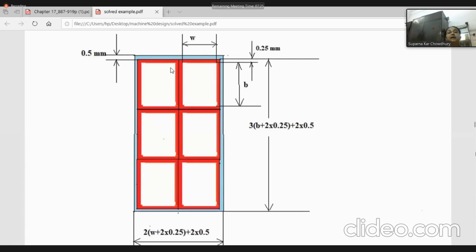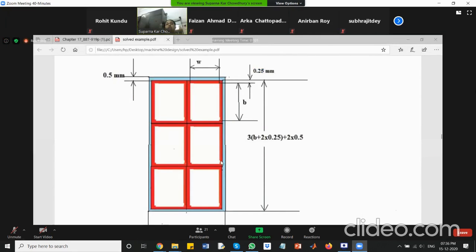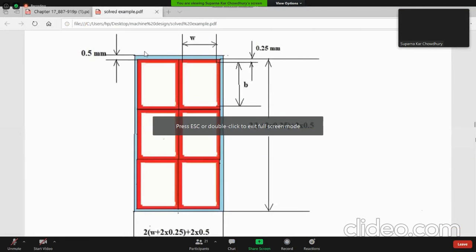So this is the bare copper on which we will have insulation. Normally this insulation is paper, double or triple paper covering, DPC or TPC. And this is the individual insulation, and this is the outer one. This is the common one, normally cotton tape.